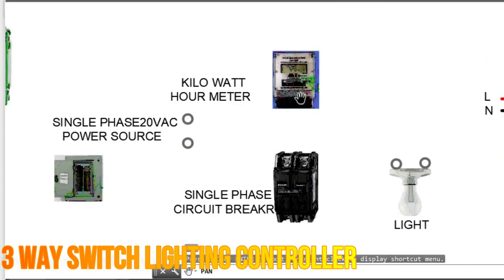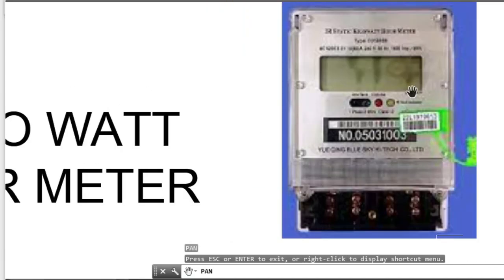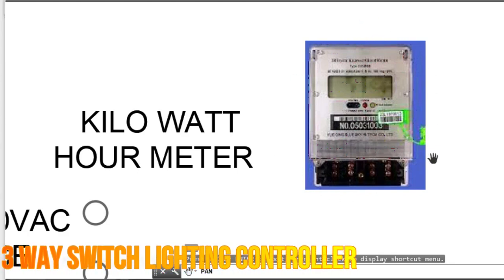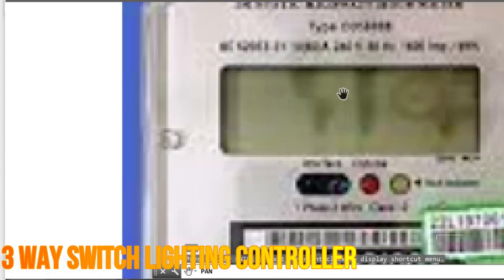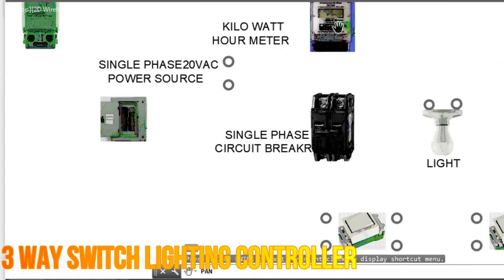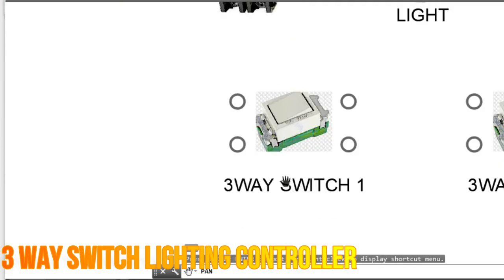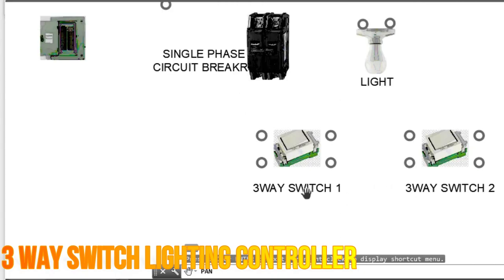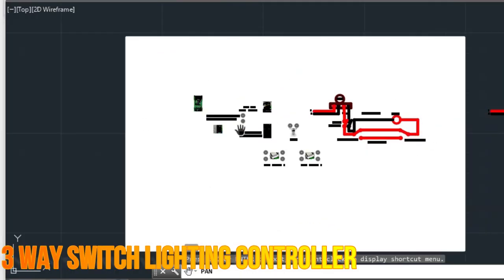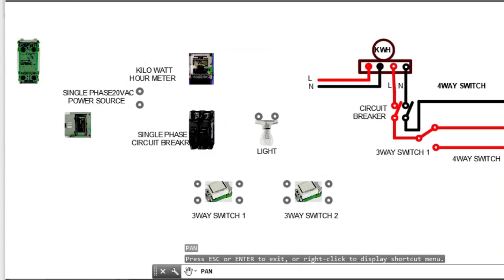As you can see here, I already set up the actual components. This is the kilowatt hour meter, which normally calculates the power consumption in your house. It will be indicated here. From the kilowatt hour meter, the wiring goes to the circuit breaker. This is the particular circuit breaker. Then we also have three-way switch one, three-way switch two, and the light. Whatever you can see in the schematic diagram is also here. I already placed it in this black diagram of the electrical components.